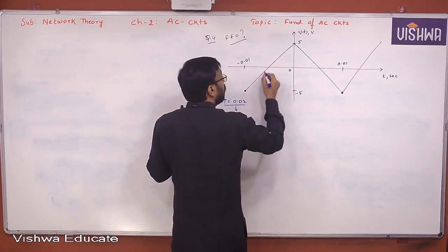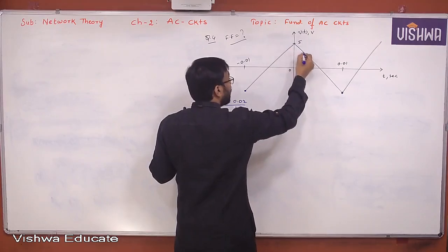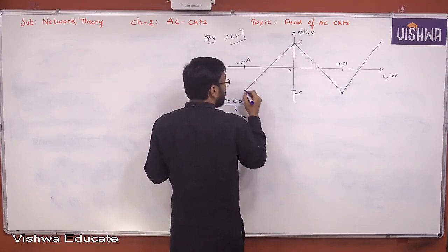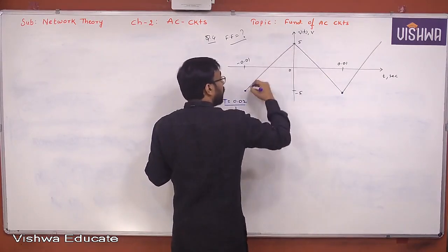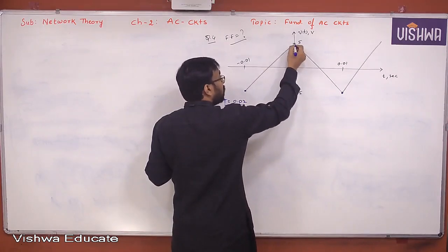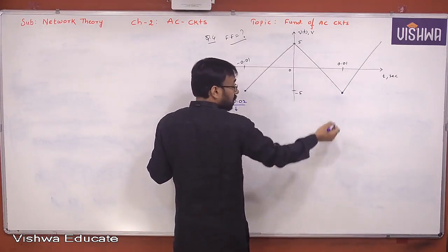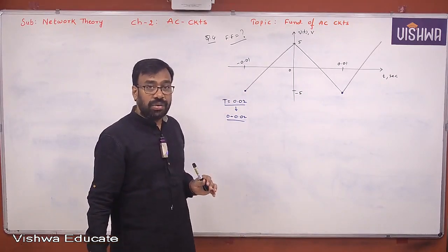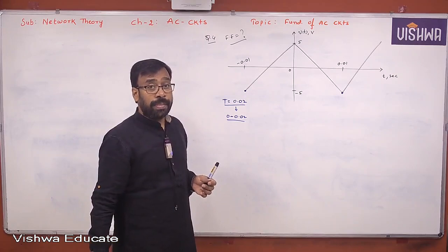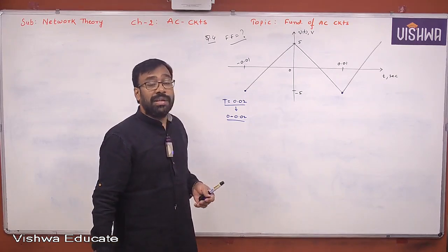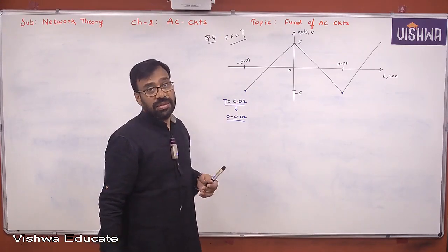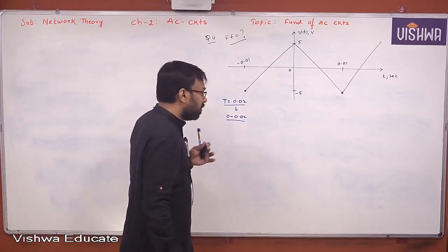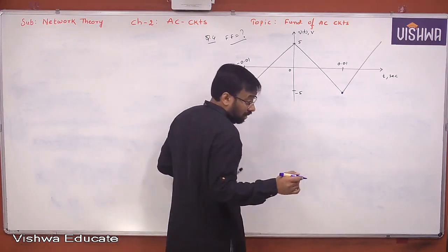What are the waveforms? It is a line with an increasing slope. This is a line with a decreasing slope. So starting point x1, y1, x2, y2, find the equation. Then go for the integration. It will take a lot of time. You will get the answer, don't worry. Then RMS also similarly. Square of that particular function and then integration. Takes definitely time. Let's go with our calculation.